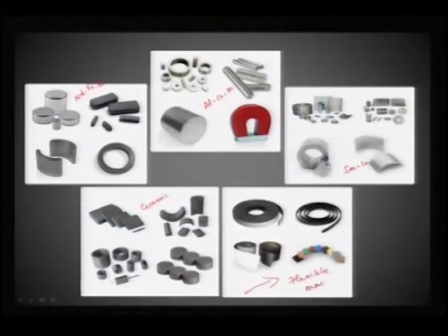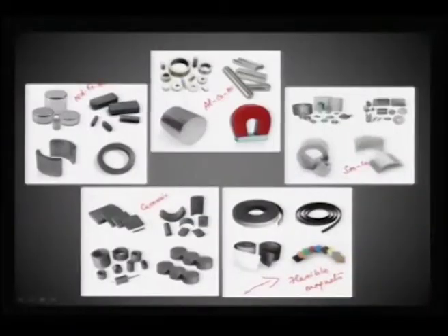Usually flexible magnets contain a polymer support where these permanent magnets can be interspersed and rendered into tapes or any other flexible shapes. So, by and large, when we think of permanent magnets, you have borides or alnico, which is an alloy, or a rare earth alloy, or ceramics. Usually these are oxides and classified as ferrites, which are used for applications.